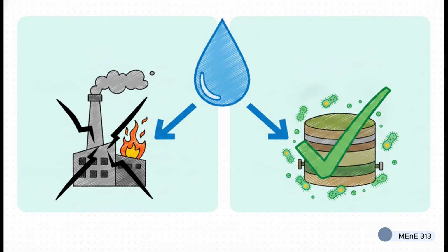All right, let's pivot a bit to Section 3, Biological Traits and Suitability. So now we're shifting our focus from burning waste to the specific properties that dictate if microorganisms can do the heavy lifting for us. And this perfectly illustrates the whole cause and effect relationship in waste engineering. Just look at how moisture behaves differently depending on the pathway. In a thermal mass burn incinerator, high moisture requires auxiliary fuel, demands drying, and tanks your efficiency. It completely ruins the process.